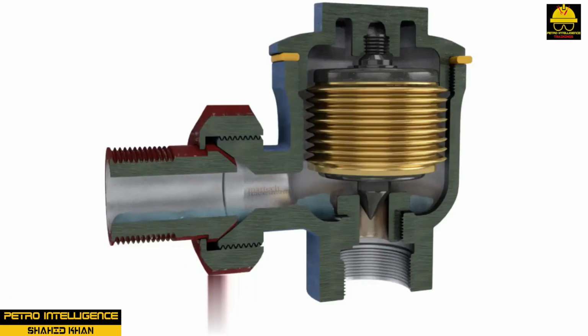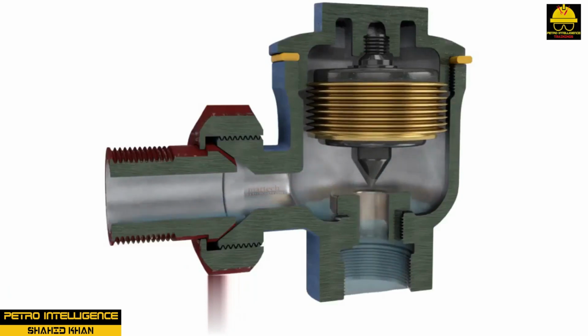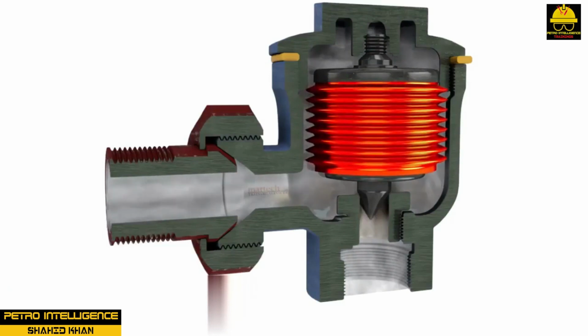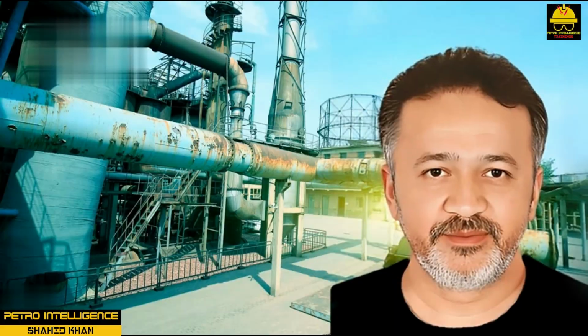Thermostatic bellows traps are used in intermittent and 5 psig or lower service. An 18-inch minimum vertical leg is required for horizontal or vertical installation. Bellows traps are self-draining when the outlet is vertical.